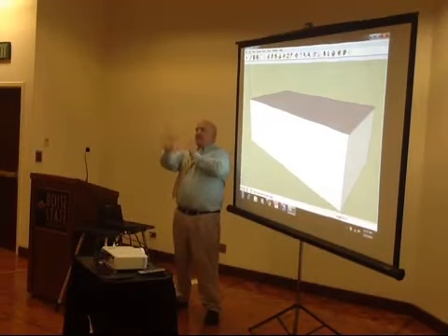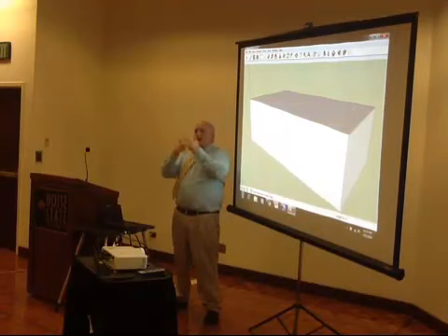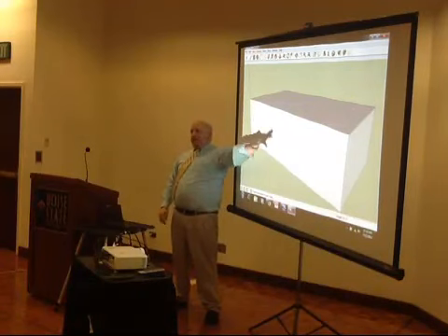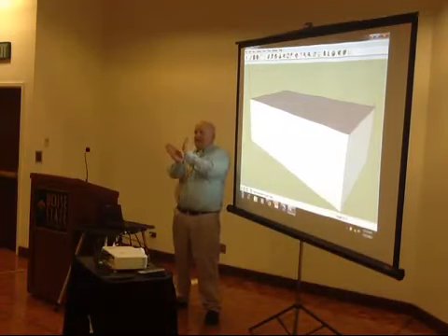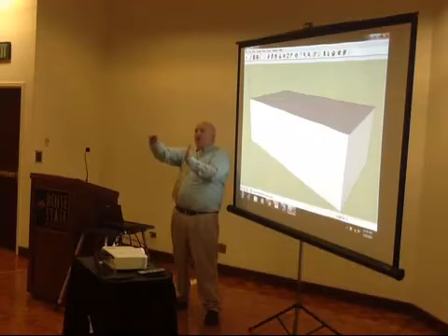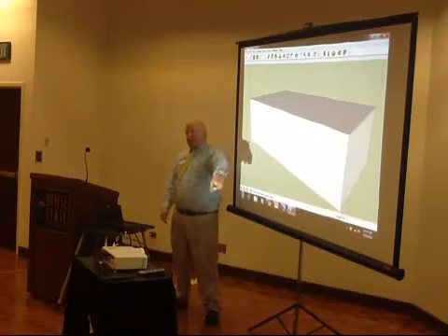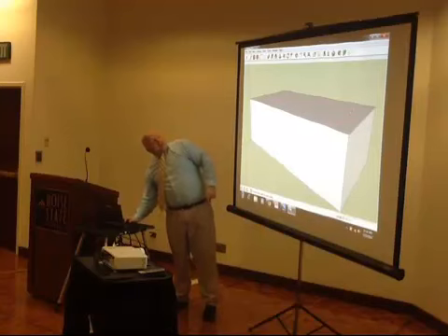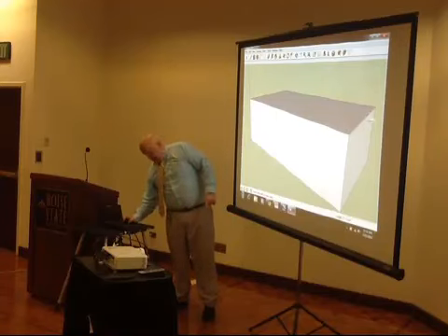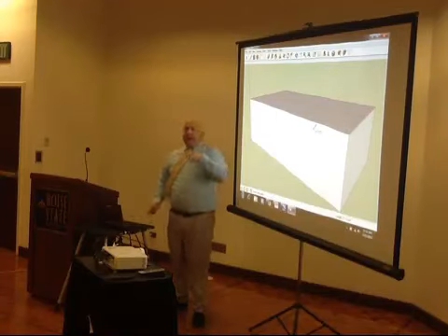It'll let us draw square and perpendicular lines very easily from that point on. That's why we orient it to those axes to start with, so that that's always a reference point for us. So I'm going to click once over here, drag all the way across till I get to the other line, and I'm going to click again. And now I have a line.